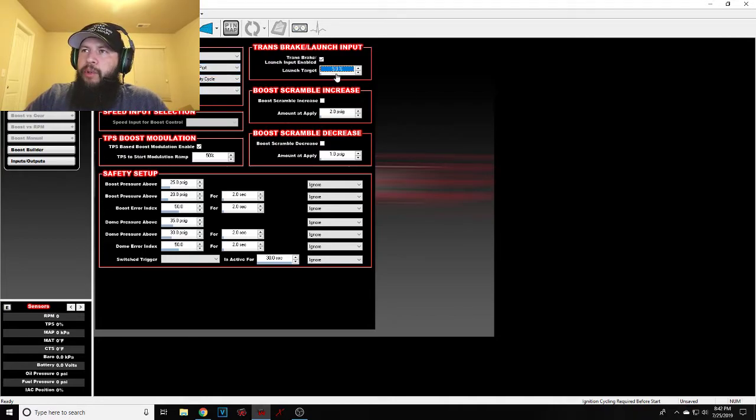So for example, when you're in open loop doing duty cycle only, let's say you're launching at 3600 RPM, and you might need 60% duty cycle to get like 4 psi out of it.